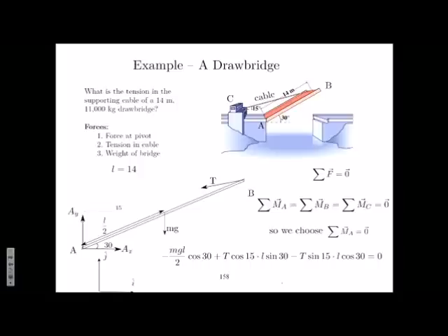Okay, so let's look at mg. So mg is entirely along negative y direction. If I drop the perpendicular from point A to mg, it will be what quantity? It will be L by 2, and this angle is 30, so this is L by 2 cosine 30. So mg by 2, L times cosine 30 is the moment of mg. What is the sign? This force is going to rotate about point A in the clockwise direction.